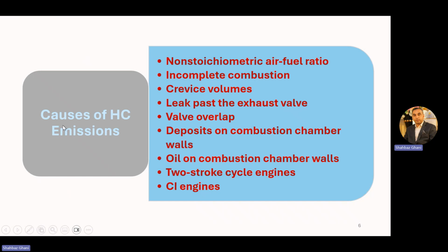Now, the causes of hydrocarbon emissions, the reasons due to which we get hydrocarbon emissions. First, non-stoichiometric air-fuel ratio: if the air and fuel are not in stoichiometric ratio, we get this emission. Second, incomplete combustion: if the piston engine is moving very fast there is less time for combustion, or if very slow, we have different combustion properties, so there will be emissions. Third, crevice volume: the gaps between the piston and the wall and the spaces in the head create a crevice volume, which is also one of the causes of hydrocarbon emissions.